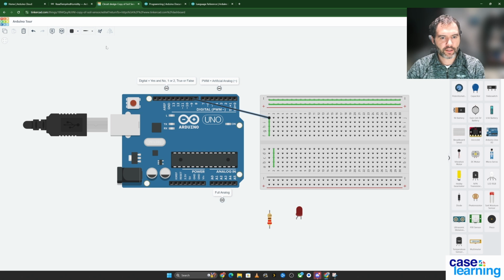Maybe you have another wire that is going from here to somewhere else, and so then the circuit would keep going along that path. So if you needed something to break it, or you're connecting something in between, that's where it would talk from one to the other. It does not reach across this little channel in the middle. You do have to put an extra pin across that, or a wire across that, or a jumper across that if you're going to connect it.